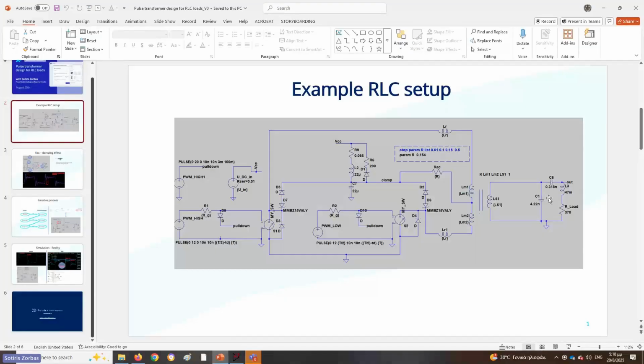You can think of it like a capacitive load, and then we have inductance in series that might be parasitic, or it might be actual leads, wires. This transducer, for example, has long wires in the application I have in mind, but we didn't care much because the effective inductance here is like 47 millihenries. In other cases, it might be a driving scheme. You may have an LC and it's ringing. How can you simulate this ringing behavior?